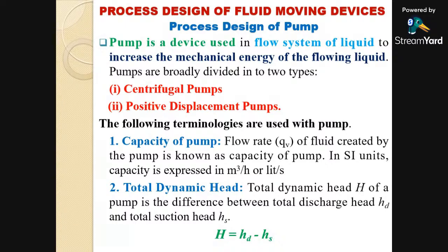The reciprocating pump is one type of positive displacement pump. There are two main types, the centrifugal pump and the positive displacement pump. Actually, there are more types of pumps available in the industry, like gear pump, lobe pump, rotary pump, screw pump, and so on. We are skipping these right now, because each may be a type of centrifugal pump or a type of positive displacement pump. The working principle for these two pumps is different.